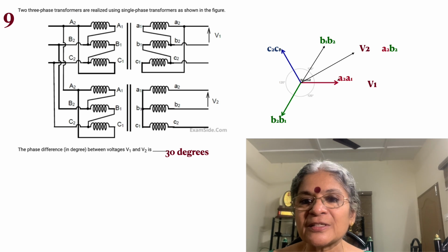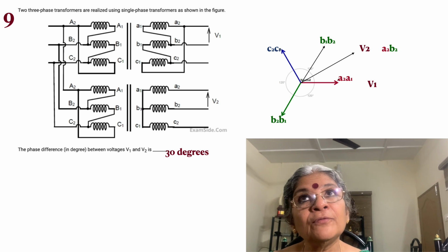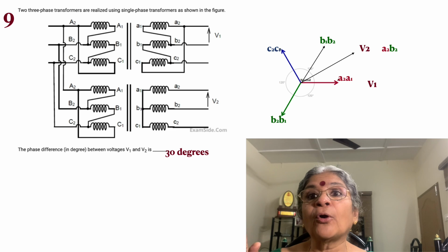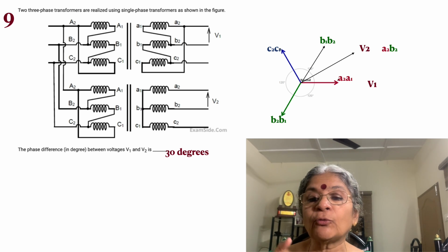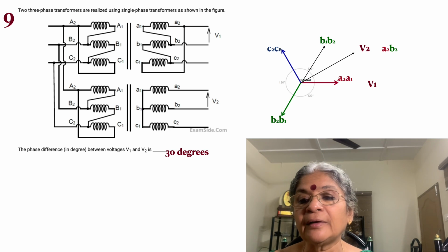Why do we draw it in this manner? Because now we need to find out which is V1. That's the reason why V1 is written with the pointer at A2, and that's why it's called A2, A1. So what is V1? V1 is just the voltage across A2 and A1, because B2 and A1 are connected together. So that's V1, and that's why A2, A1 describes V1.